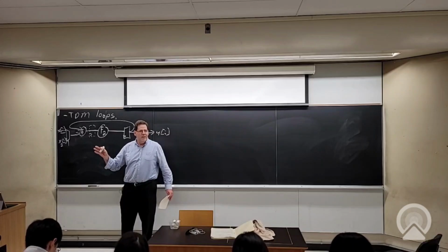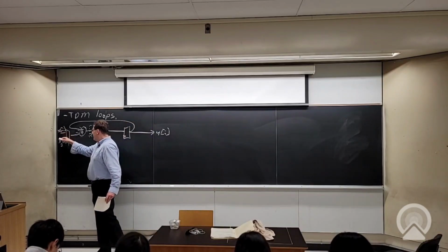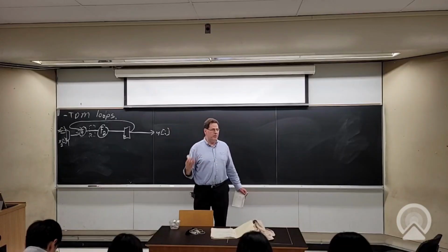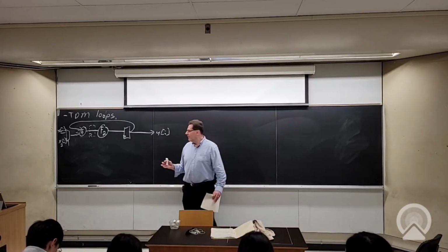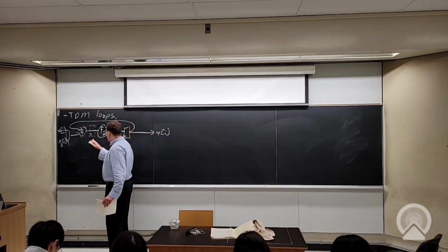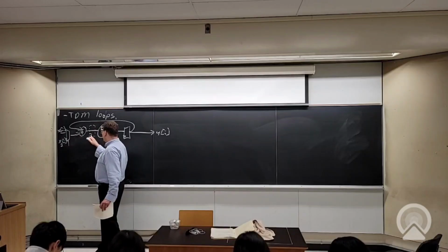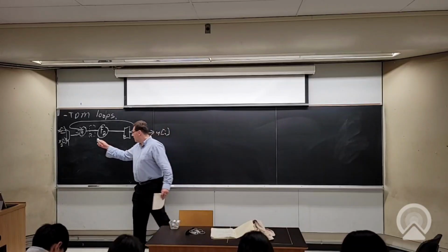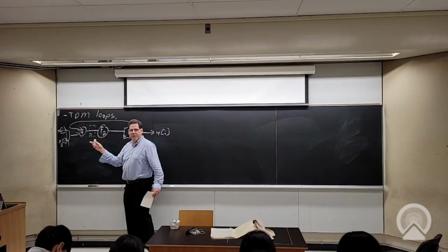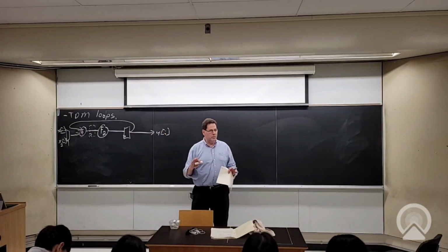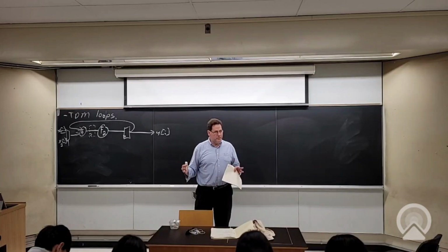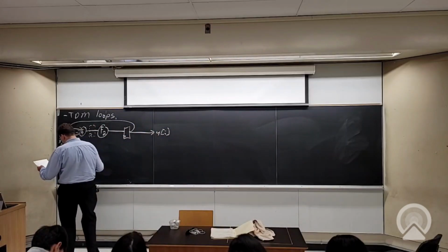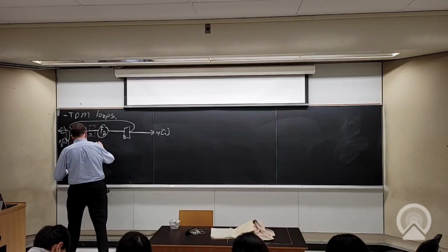Does that make sense? So the time domain multiplexing that I did here has enabled me to basically pipeline this more deeply. And I have to do both at the same time. If I want to do this time domain multiplexing and make it work, I need to put this register in. But the combination of the time domain multiplexing and putting this extra register in, which doubled the latency around my loop, they've effectively canceled out the impact on one stream. So now it still does the same thing for each stream.